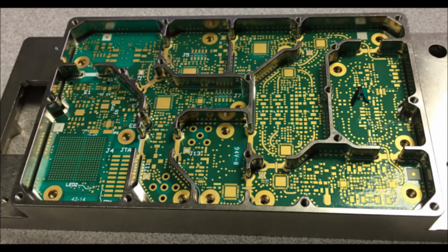Looking at the image of the chassis and board again, we see that there are openings in the walls where different parts of the PCB are connected to each other. We will call these openings gates. When the unit is fully assembled, there will be a small machined metal part that slips down into the gate openings and makes contact with the PCB to create a complete EMI shield.